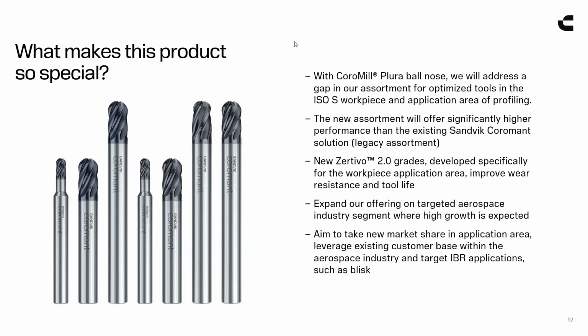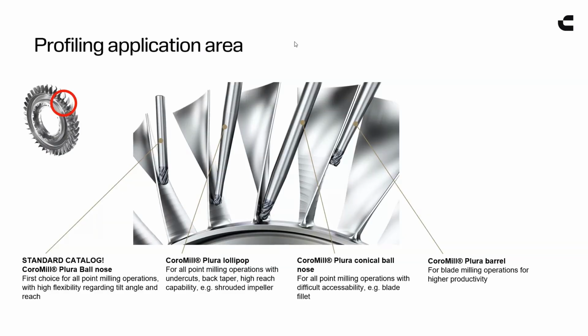The edge prep, the land, the center cutting at the tip, the actual hone and the grind on the curvature is made to a much tighter tolerance than it otherwise would be, so that it's all geared towards making fantastic 3D profile shapes. Just like you see here on this example, these blisk fins.